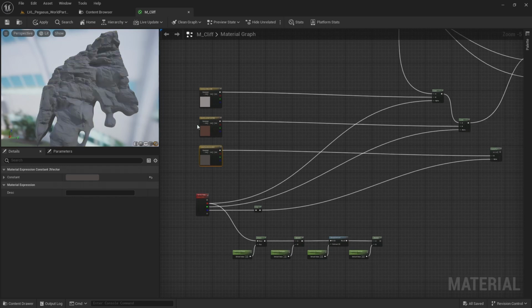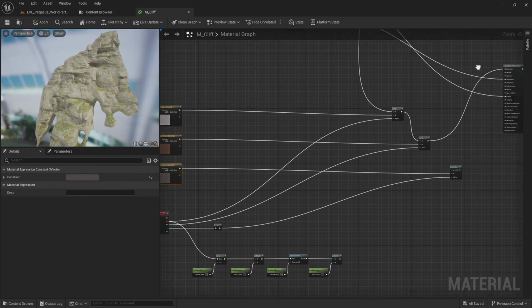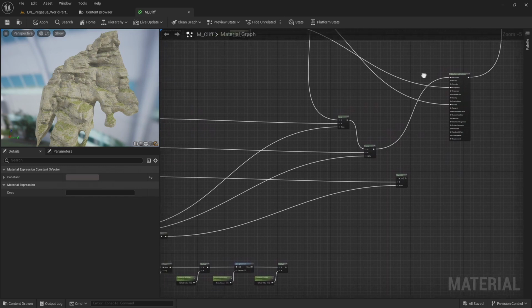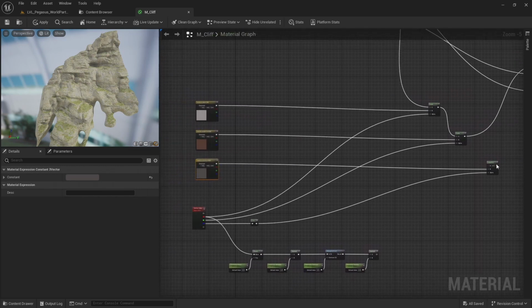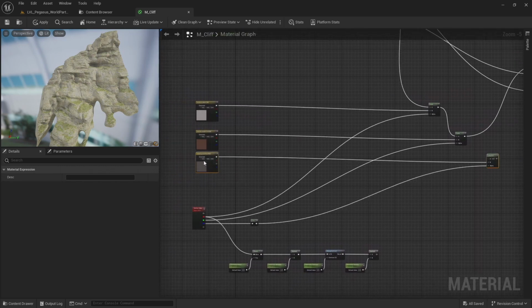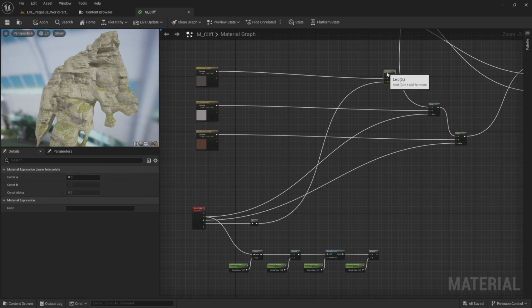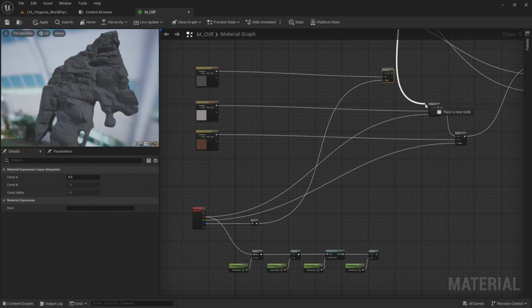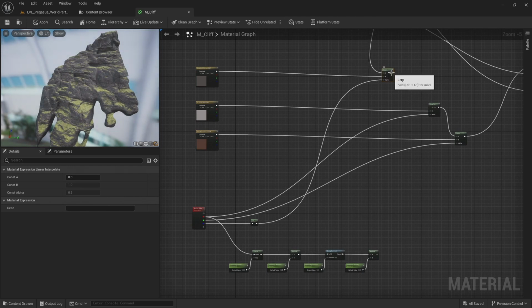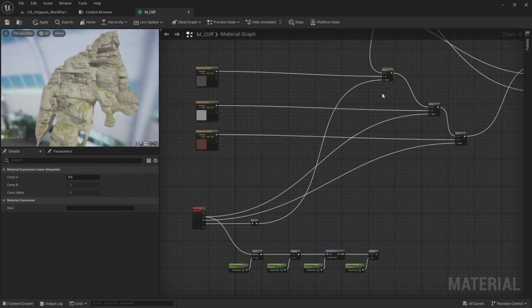So now the color for the concavity is going straight into the base color on the make materials attribute, and I'm going to bring this color and its lerp up to the top, and now reconnect this input, again holding Control and left clicking and connecting that wire to the first lerp. Now I can reconnect that wire for the ambient occlusion lerp into the lerp for the convexity.